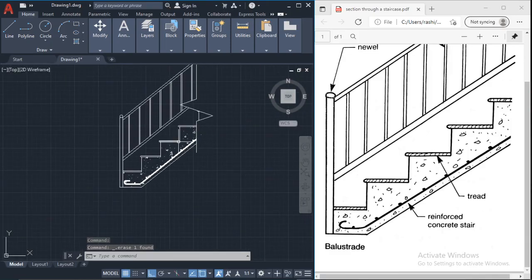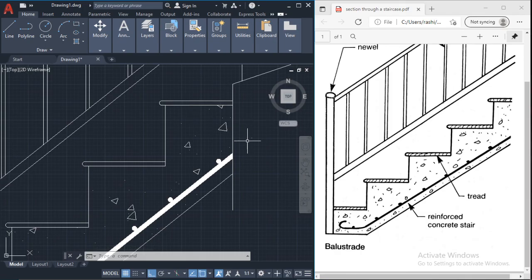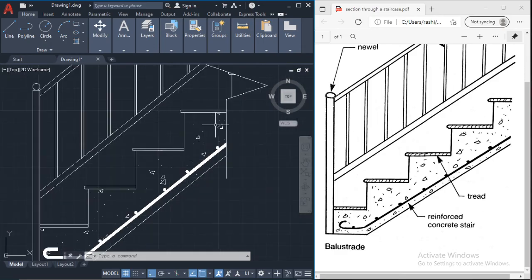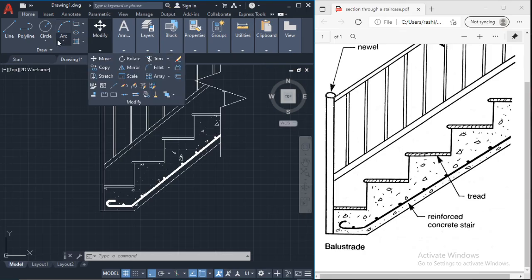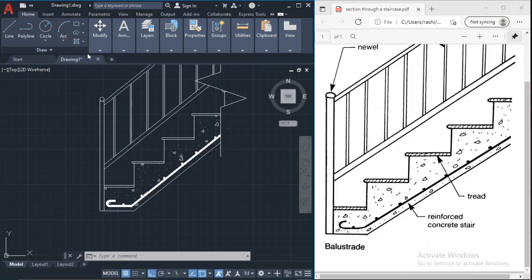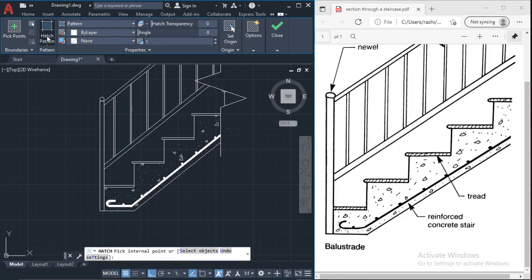All right. Now this is hatched in wood. I don't know if there's a wood hatch in AutoCAD. The closest thing I see to wood in AutoCAD is ghost wood. So we'll use that, I guess. Or you can select sketch, and you can draw these little curves here. Looks like wood, and then just copy it from one, bring it to the next one, and so on and so forth. Or you could also use a spline to get the little curves, and then you copy them to different places. But we're just going to use ghost wood because that's the closest thing we have to wood in AutoCAD here.